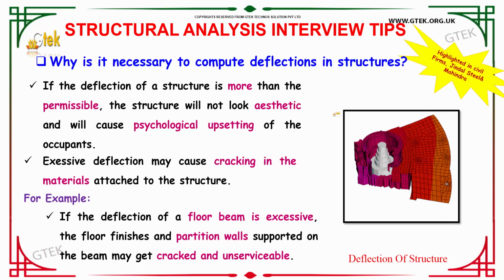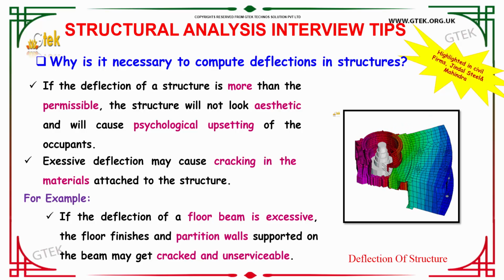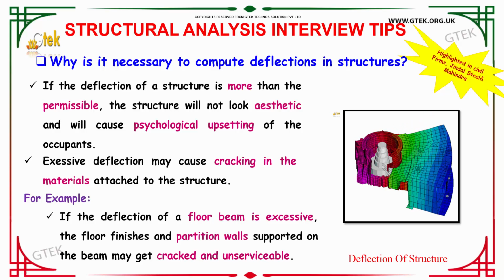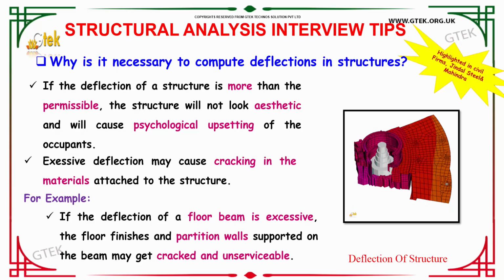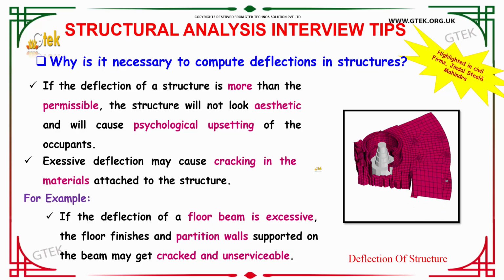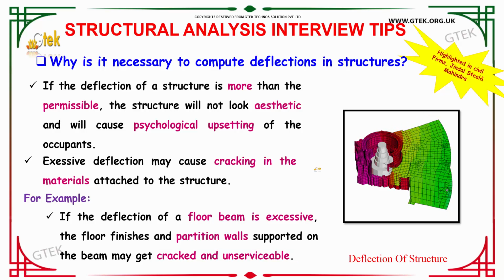For example, if you see the deflection of a floor beam is excessive, then the floor finishes and partition wall supported on the beam may get cracked or unserviceable. So these are the risks of deflections in structures.